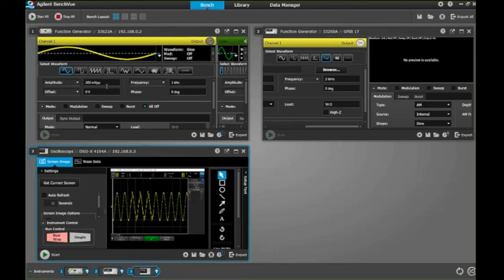What type of file format are the Arbs for Trueform? Oh, okay. So the file formats for Trueform are actually in this proprietary format called .arb files or .barb files. A .arb file is a text viewable ASCII-based file format. The BARB is a binary format. So if you want, the BARB file format is faster to download. So if you do have very large waveforms, you're going to want to use a .barb.